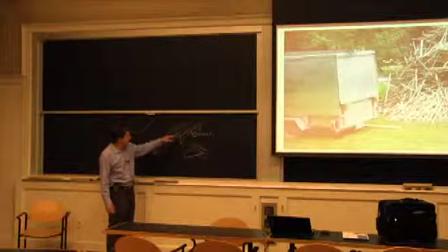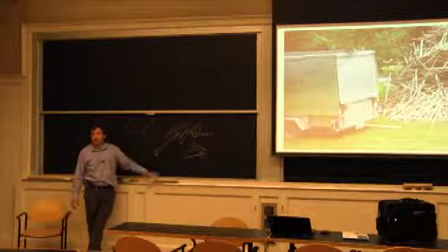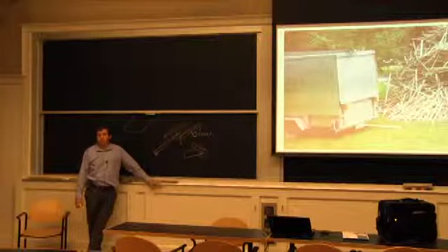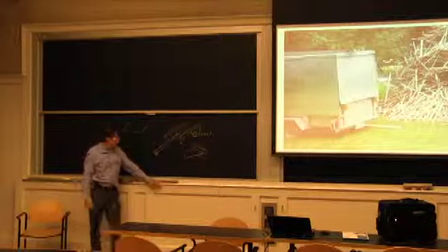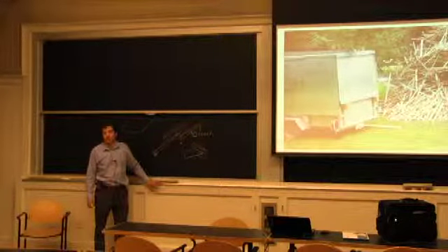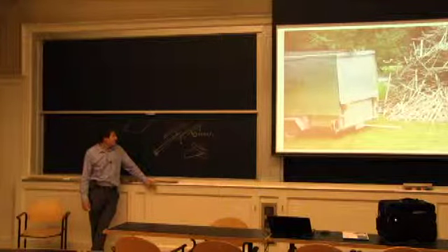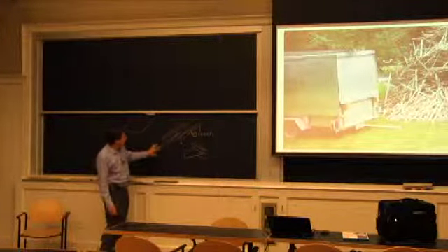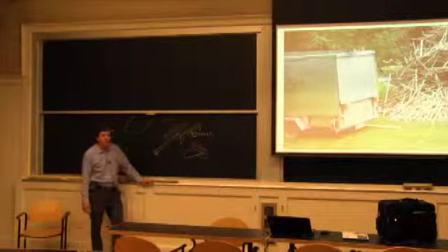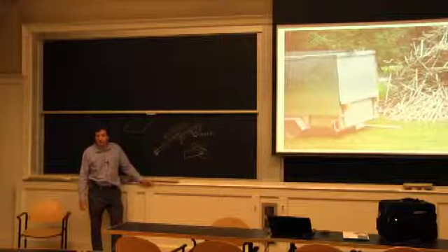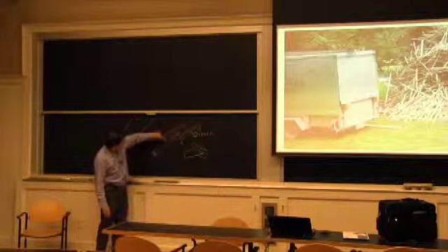It's only when you hit a big bump on the road that there's really something going on here with strength, that you have some dynamic factors that add and could result in getting close to the yield strength. Now, in retrospect, when I talk about practical design, this member here, if I wanted to optimize it, and this was a race car, I would make it thicker here.